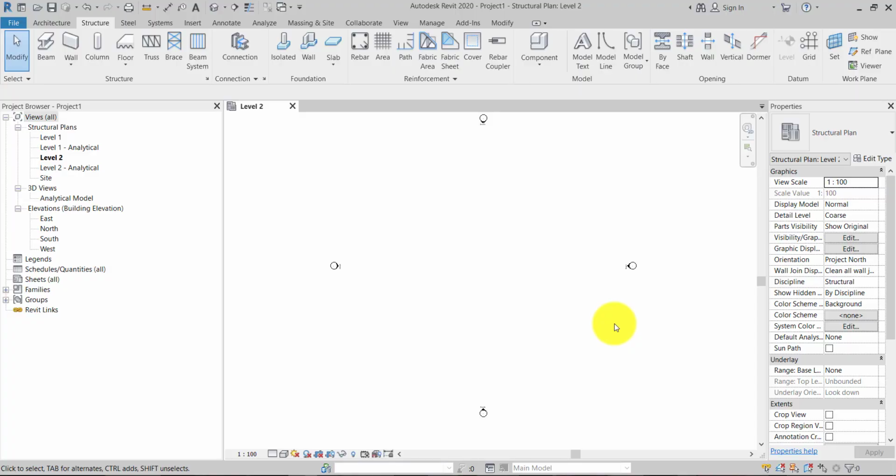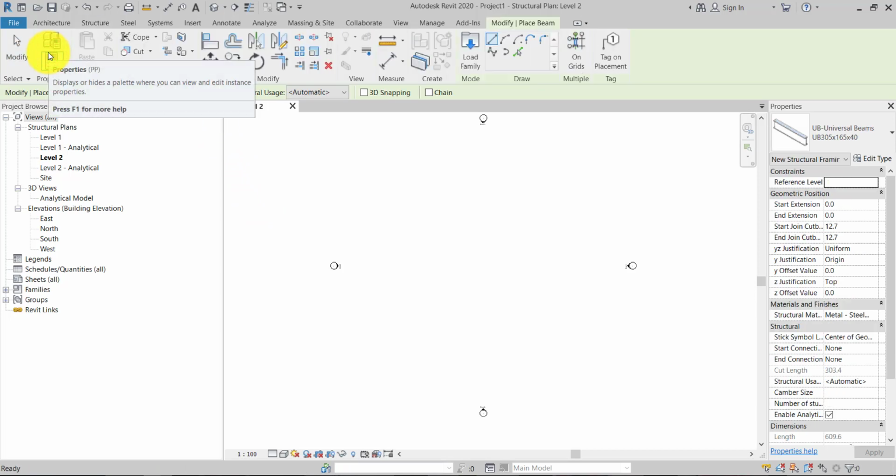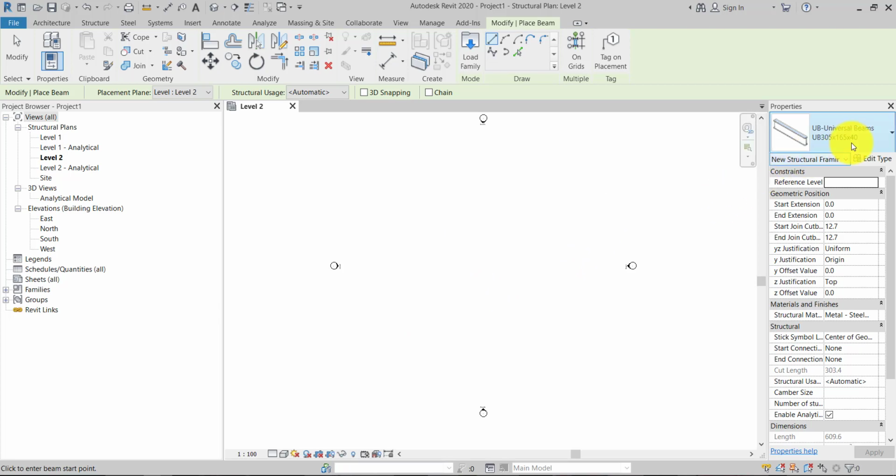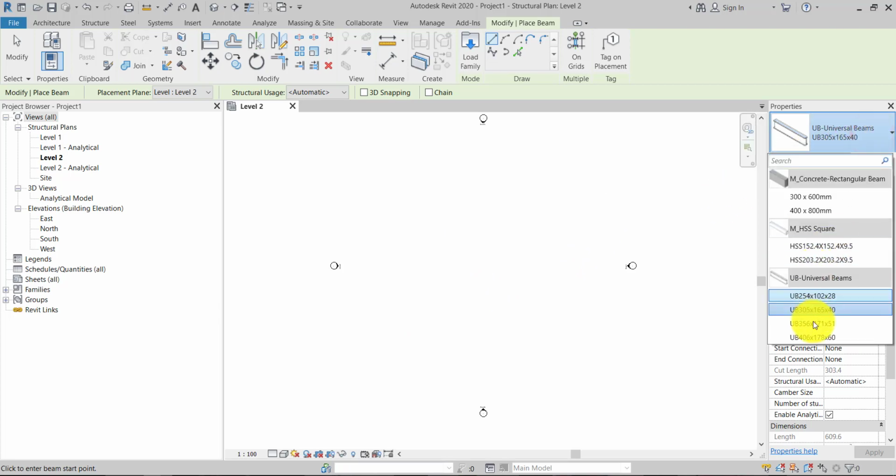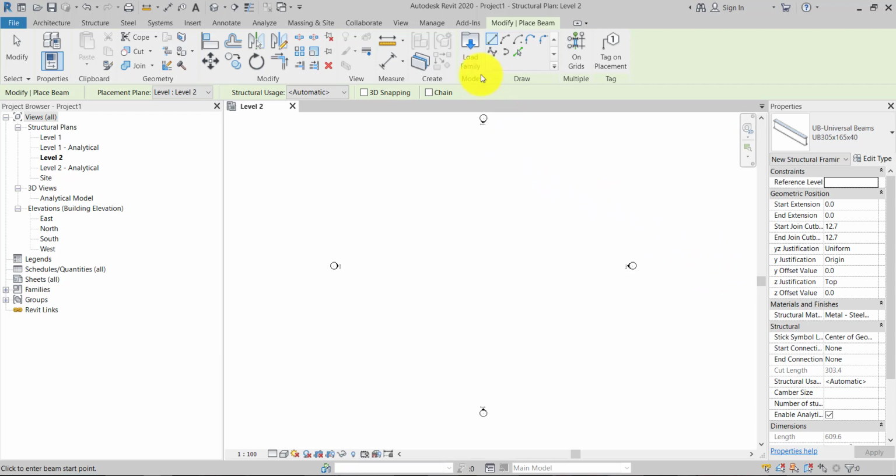In this video, I'm going to show how to add a parameter that automatically calculates the cross-sectional area of a hollow steel, and this time we are going to study the circular hollow steel, CHS or HSS round. So from this default project here, let's select the circular hollow steel, which is not available in the default project. So we will need to load a family